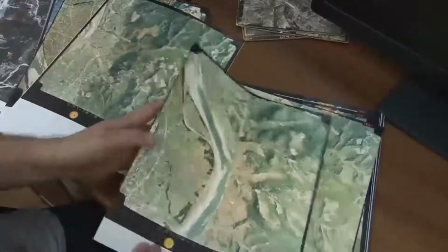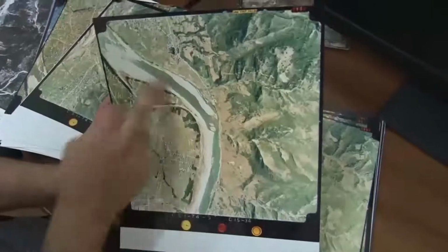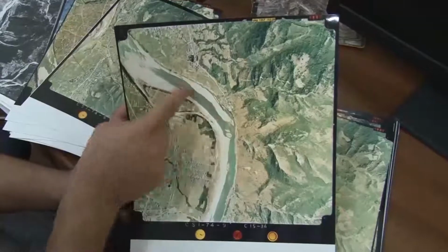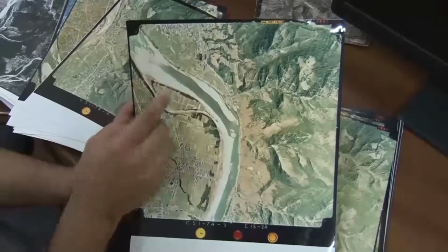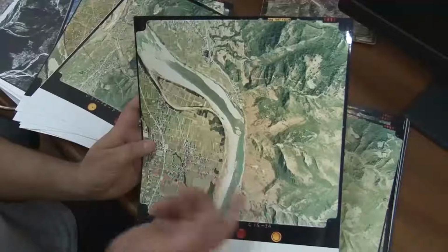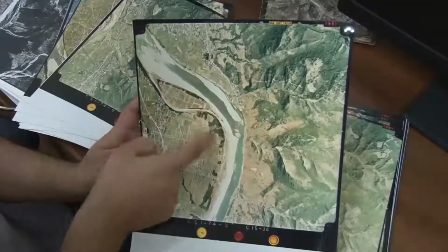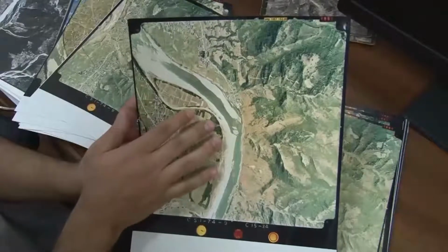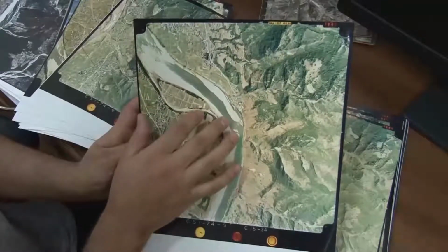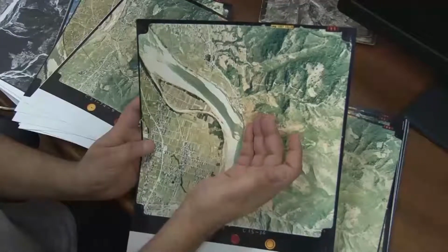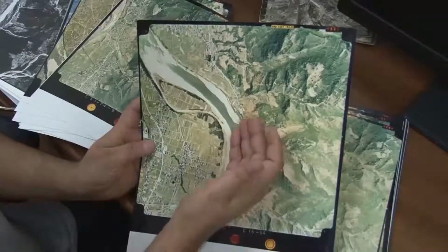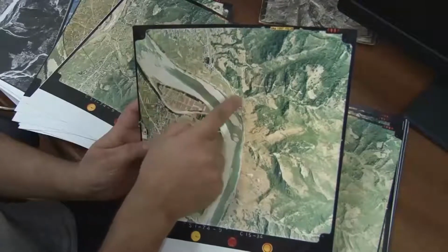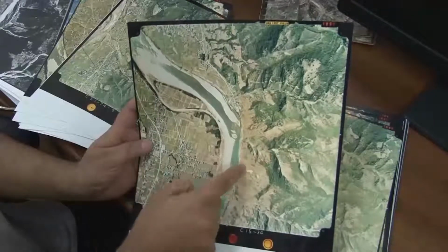So similarly, this is a very good example of a meandering channel, where these whitish islands are the sand islands, which are also known as point bars when they are inside. At the inside of the meandering curve, a river deposits the sediment. At the outer bends, it erodes. And due to erosion, there is a shifting of the river channel.